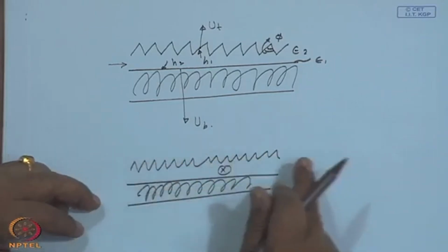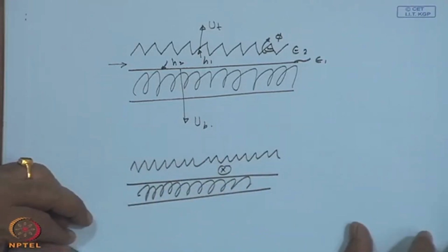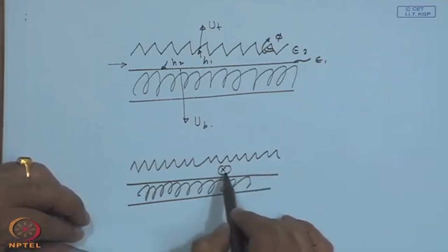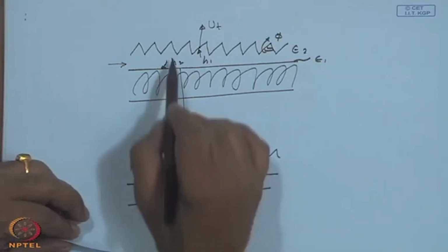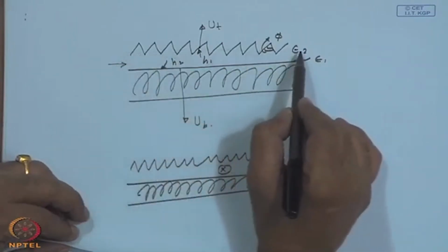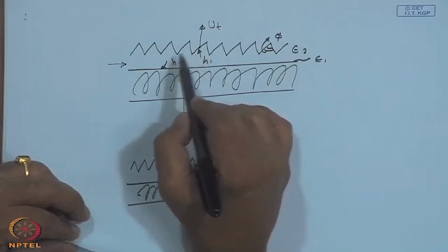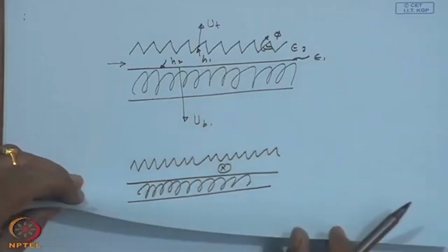Still it has a larger extended area compared to a plain plate. Consequently, it may be having better heat transfer characteristics than a simple flat absorber. However, here the phenomenon is different. It aids augmenting heat transfer by breaking the development of boundary layer as well as providing mixing of the fluid.